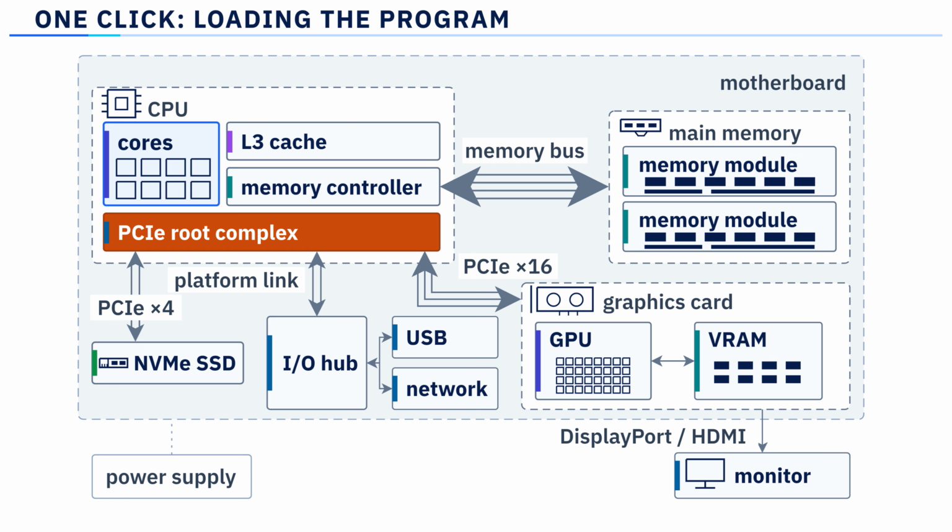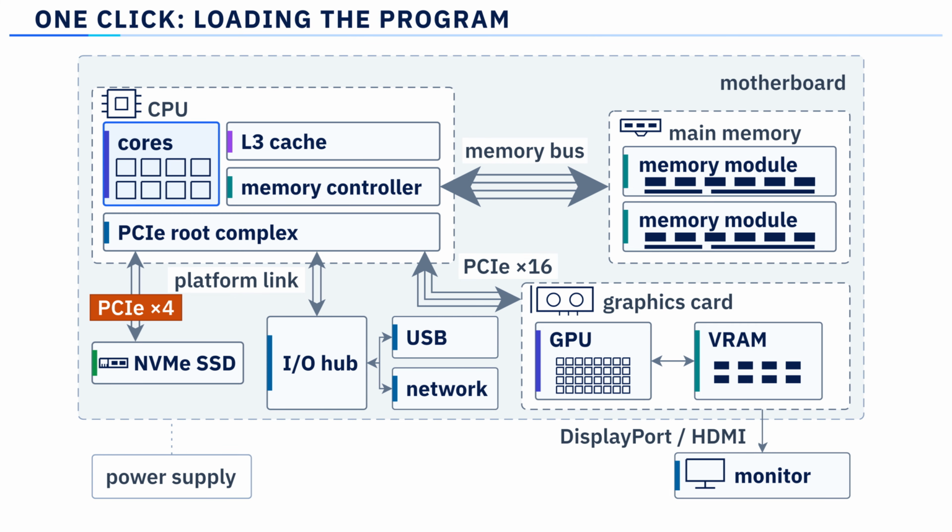Those block requests leave the CPU through the PCIe root complex as NVMe commands. The drive is never told the file name. They go down 4 lanes to the drive. More lanes carry more data every second, and the drive gets 4 of them. The drive's own controller reads those blocks out of its flash chips. This is the slowest step of the trip.